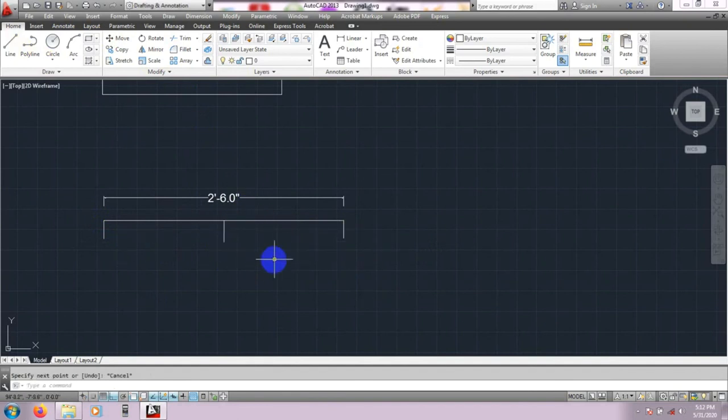Now I will show you another thing. Again press SC, then enter, then select the object. This is our object, then again enter, specify the base point. If we select that point, I have told you that in that direction it will increase. So select that point and specify scale factor. Sorry, I will use scale factor suppose 2. Then just see it's increasing in that direction, from here to here. Okay, so in this way you can do your work.